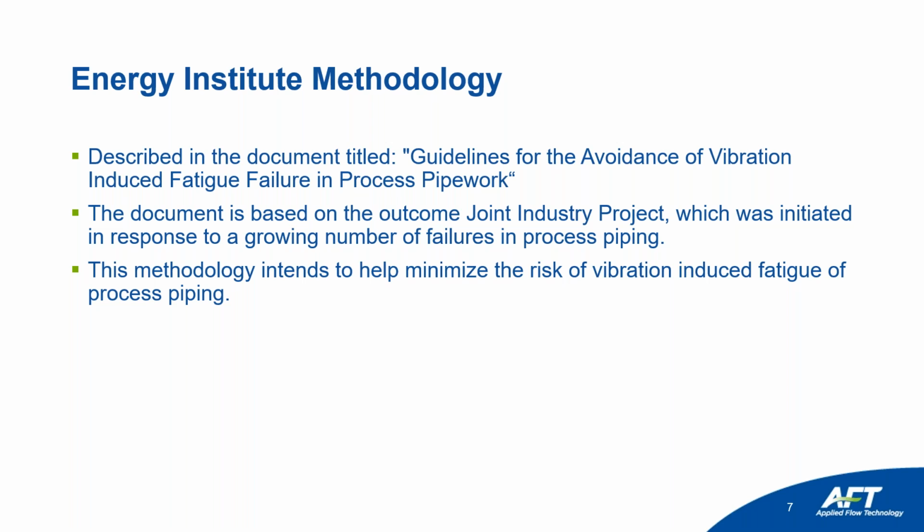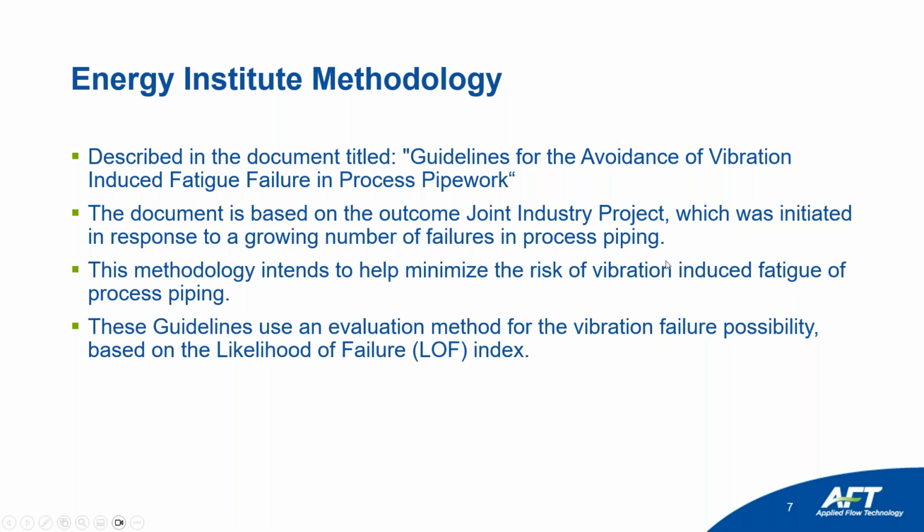This methodology intends to help minimize the risk of vibration-induced fatigue of process piping. These guidelines use an evaluation method for the vibration failure possibility based on the likelihood of failure, which is called LOF index.